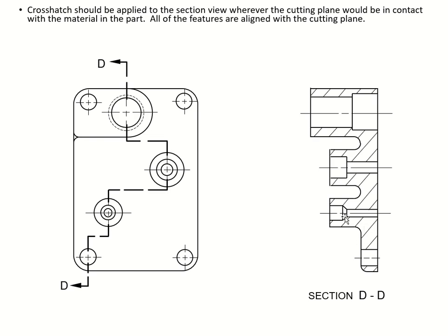And then after you finish thickening all the hidden lines, we are going to put all of the crosshatch for the exposed area, leaving all of this longitudinal. Features like the hollow cylinders, you don't need to crosshatch. These are just holes, so you don't have to crosshatch.